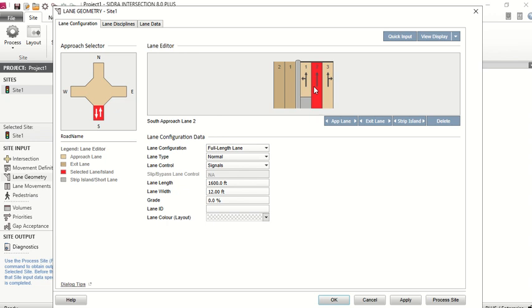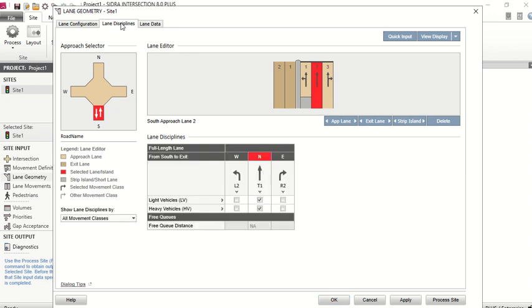So you may have seen sometimes for left turning lane, we have an island between the 2 lanes, a small median. Okay, that small median is called a strip island. Okay, so again, you can add a strip island on the left hand side or on the right hand side. Obviously now you cannot add an island in this case, right? An island in this case will not make any sense. Okay, because this lane is for straight, this lane is for straight. Okay, but if I change the movement, then an island can be given.